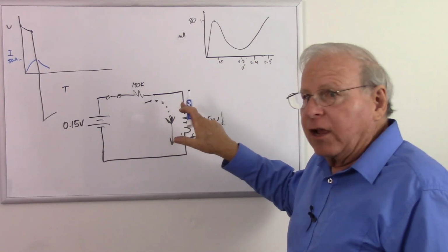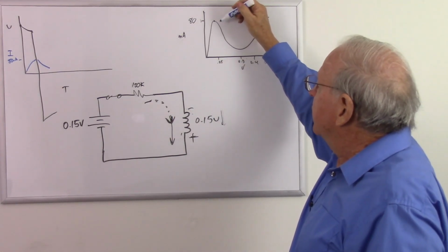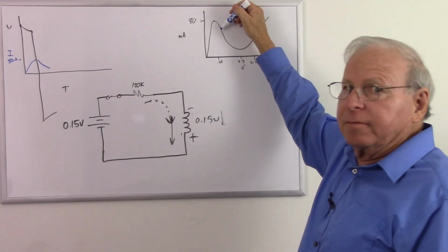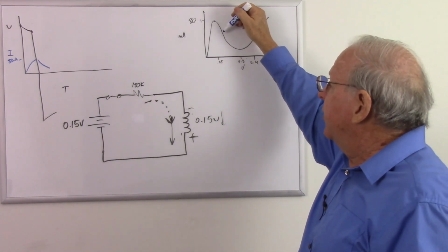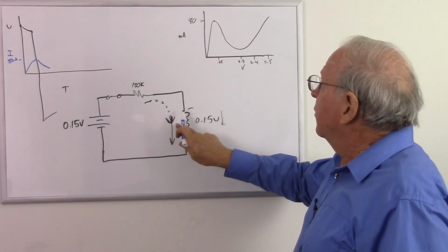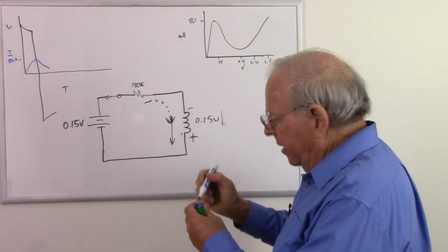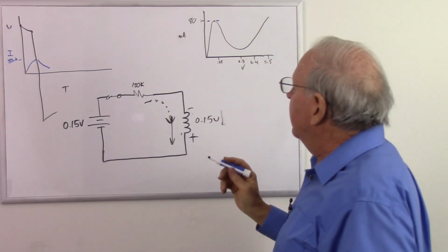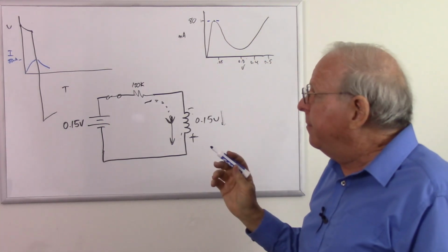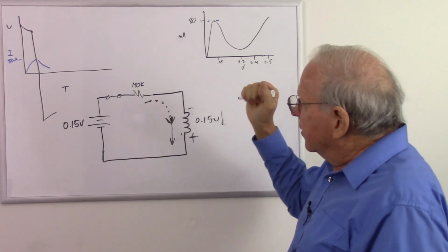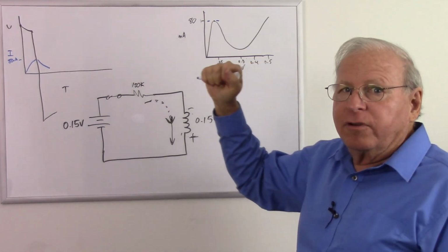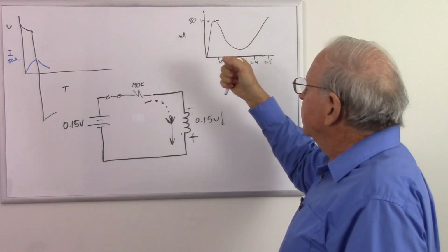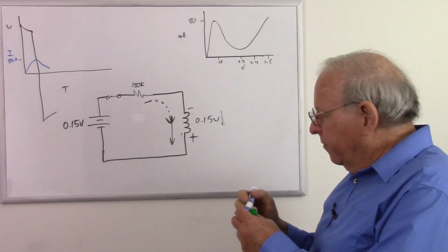The coil is not going to allow that current to go down. So the tunnel diode, as the voltage goes up, it would like to just increase its resistance and allow that current to go down. This will not allow the current to go down, so we're stuck. Let's do this in blue. We're stuck up here at approximately 80 millivolts. Cannot change rapidly. The little green man is increasing his resistance tremendously right here, trying to make that current go down. Okay, let's stop and take a look at what we've got going here, though.